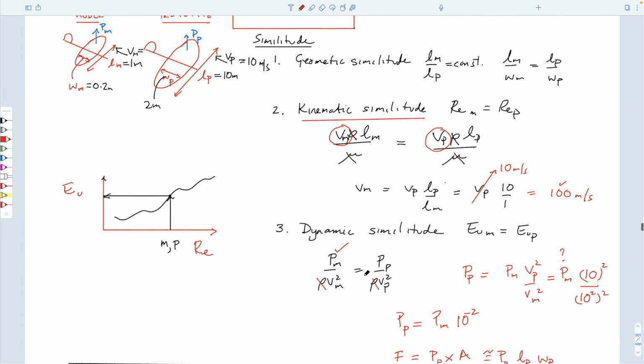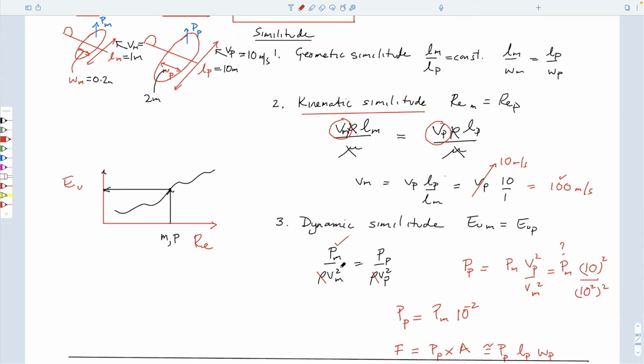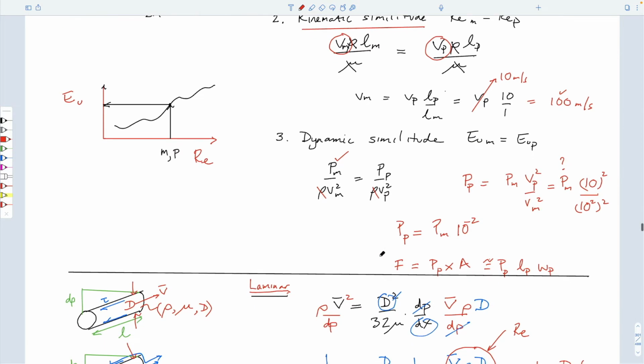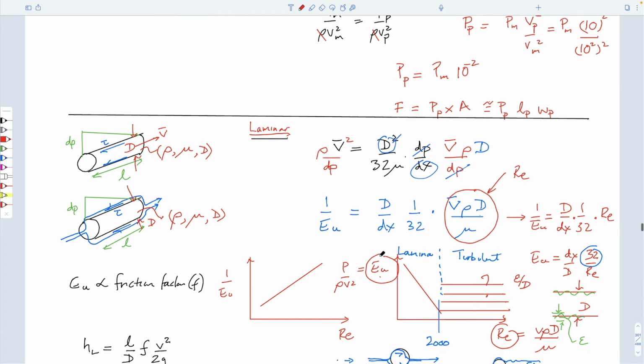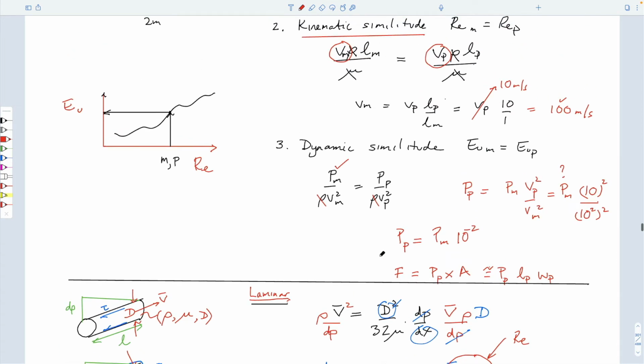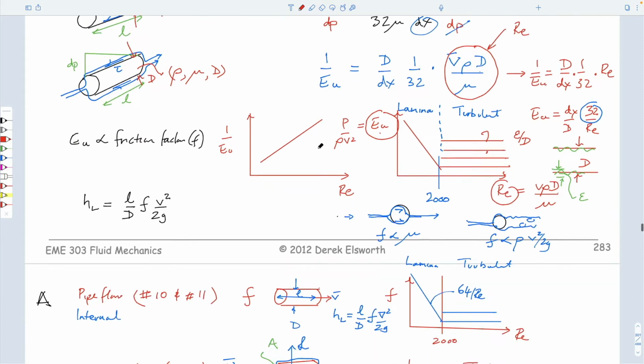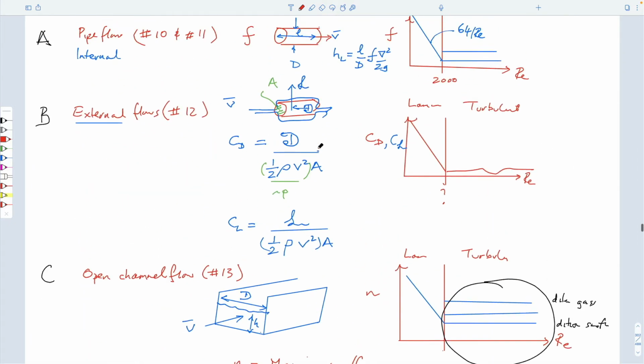And if that is the case, then the pressures or forces that you'd measure on your model can be directly translated into the forces on your prototype. And therefore you could compare those with the strength of the prototype. And you might be interested in other things. Of course, this says nothing about vortex shedding, which, if you're putting something into resonance, there has to be some feature of the behavior that must relate to that vortex shedding. Nothing about which is said here, but it is an extra wrinkle. And so that's what we talked about last time.